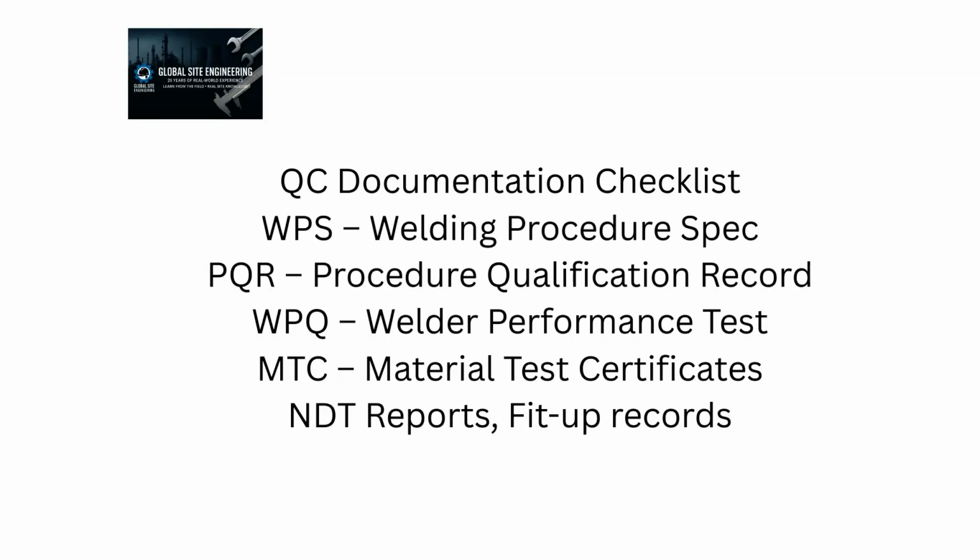QC documentation. A good QC record includes the WPS Welding Procedure Specification, PQR Procedure Qualification Record, Welder Performance Qualification, Material Test Certificates, and fit-up and dimensional reports before and after welding.